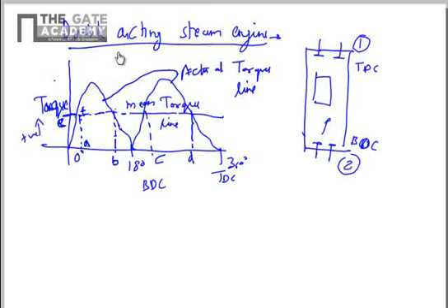Then you have F where it cuts the actual torque line first, then a peak, let's say G, and then again the mean torque line cutting, then it goes down to the bottommost point, let's say P, and then again cutting the second portion of the torque line, let's say this point is J, and the second peak is K. The fourth point of cutting the torque line is L, and then at the TDC again, at 2 pi degrees, let's say Q, and again here this point will be E.